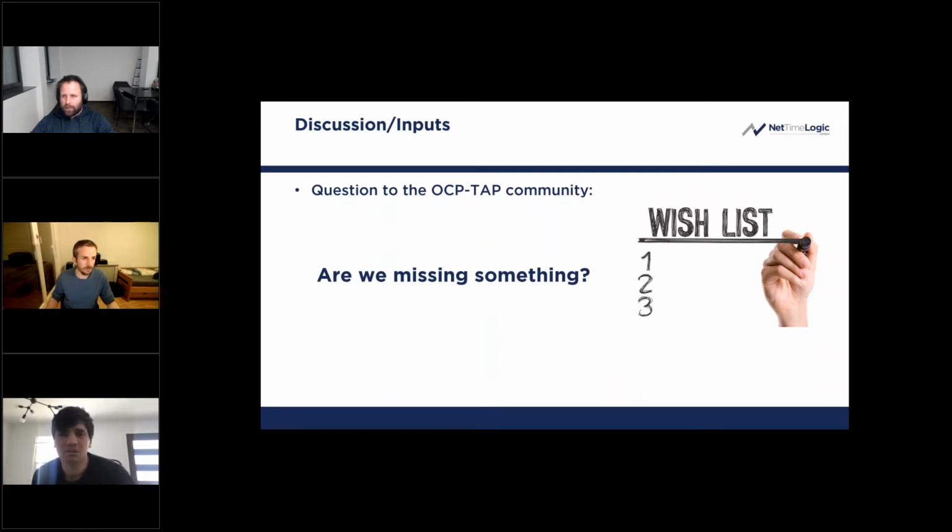Okay, so regarding form factor, we don't have any restrictions. You can pack it as small or as big as you want, as long as basically the same interfaces are there. And if you connect it to the same pins on the FPGA, you wouldn't even need to adapt the FPGA design. If you change pins, of course, we need to adapt the pin out. But other than that, I don't see anything that would block you from doing that.